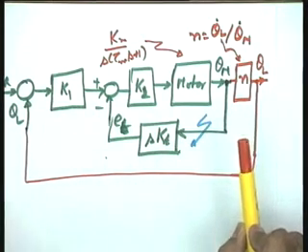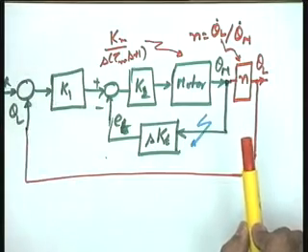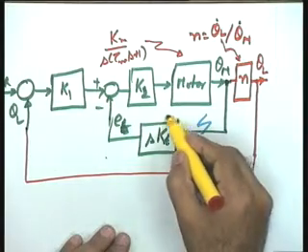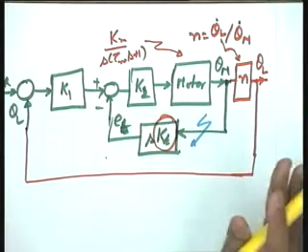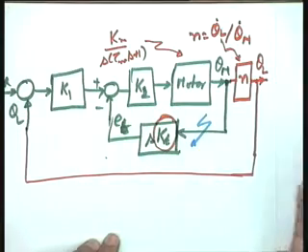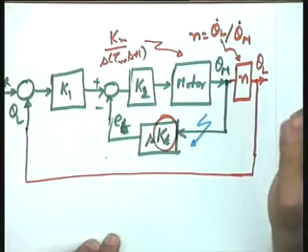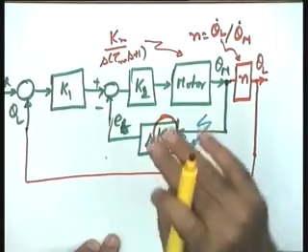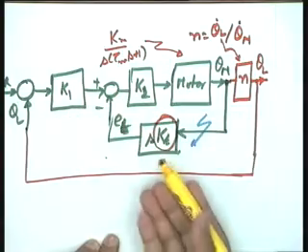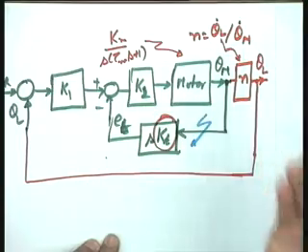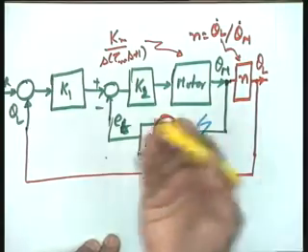It means basically, I think the point is right. Basically, it will continue to act as a position control system. The only thing is this, that this Kt, by proper use of Kt, you are controlling the damping of the system, because this is also controlling the damping. A derivative feedback, please see, like back EMF, the derivative feedback is also controlling the damping of the system, because after all you are giving a signal which is proportional to speed. Back EMF is also a signal which is proportional to speed.